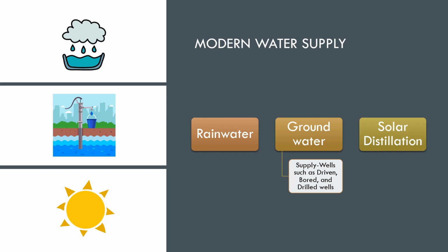And then solar distillation is a process used mostly in remote areas where there's limited access to fresh water. It's a really simple process that involves evaporation and condensation. Essentially there are black bottomed vessels filled with water and topped with clear glass or plastic. Sunlight gets absorbed by that black material and speeds up the rate of evaporation. The evaporation is then trapped by the clear topping and is funneled away. But most pollutants do not evaporate, so they're left behind.